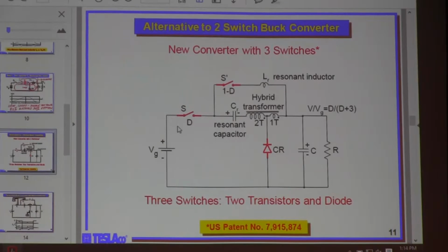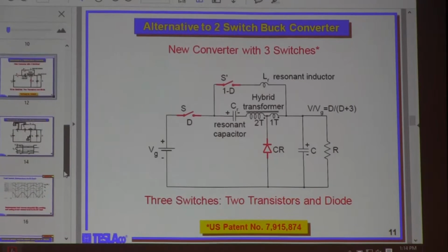And these two switches, they can be 48 volts. They're rated for 48 volts. How bad is that? And those two switches, when the next one is down to ground, they are in zero voltage switching mode, you know, and you don't have a spike. You saw it, right? I showed it on a simulation.